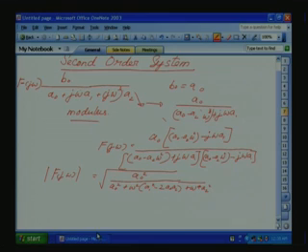Now as the frequency increases, we want this term to disappear, so that still at slightly higher frequency it should be 1. The condition is B0 is equal to A0. The second condition is that we want this middle term to disappear, so that means A1 square should be equal to 2 A0 A2.